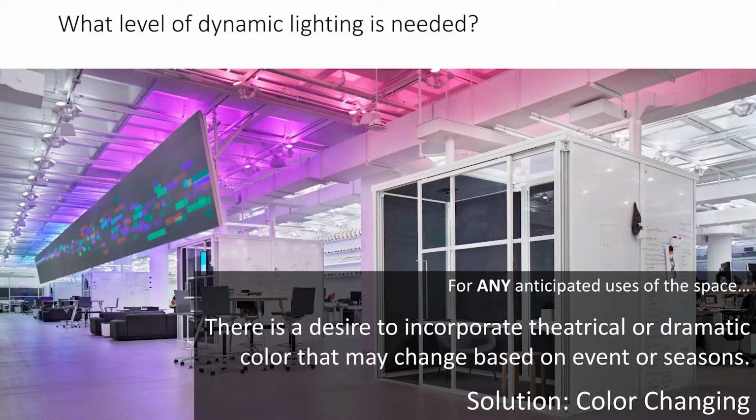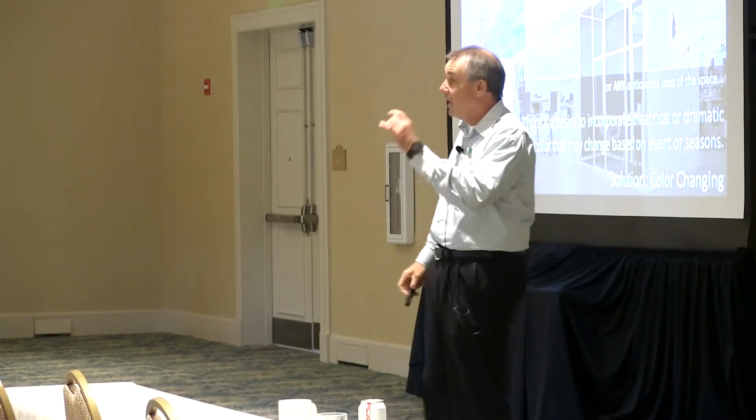So if I had a fixture that had a green LED, a blue LED, a red LED, and a white LED, this is the black body curve, I can essentially drive the fixture to anywhere inside that triangle with, if I choose, high quality white light.